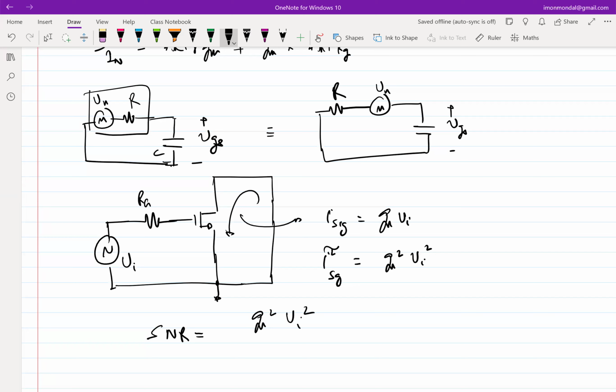And if this is a sinusoid, then I'll have to find the total power by finding the integral and all those things. If I am looking for the entire band, the power contained in the entire band for the signal, I have to multiply with the bandwidth, right? The same thing I have to do for the noise. So I'm doing some ratio on the top, some ratio on the bottom. If the bandwidth is the same for both cases, I don't have to bother about the bandwidth, right?